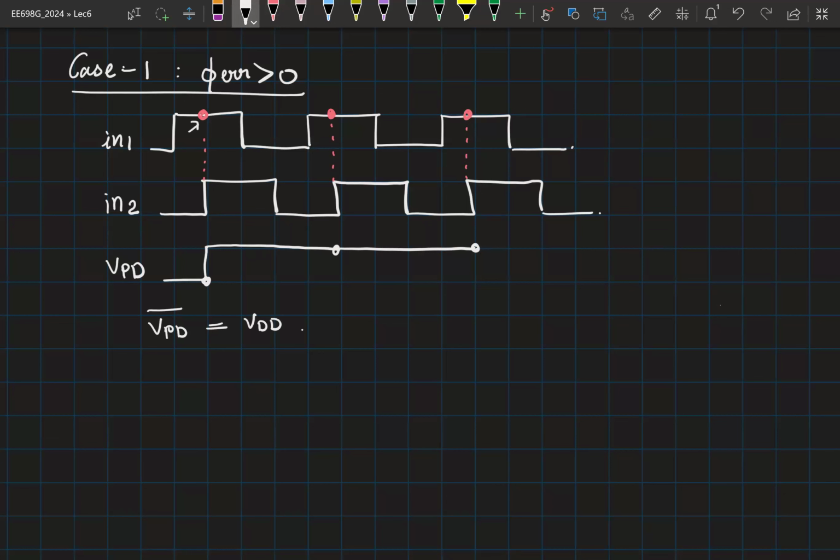So now imagine pulling this input waveform to the right. For what value of delta t is this output going to change? Yeah, till pi or T naught by 2, it will remain as 1. After that, it will begin to sample 0. Now let's assume, is that clear? Up to T naught by 2. Now imagine pulling it further. Till what point will it be 0? Till T naught, right? Till 2 pi. After that, it will again become 1.